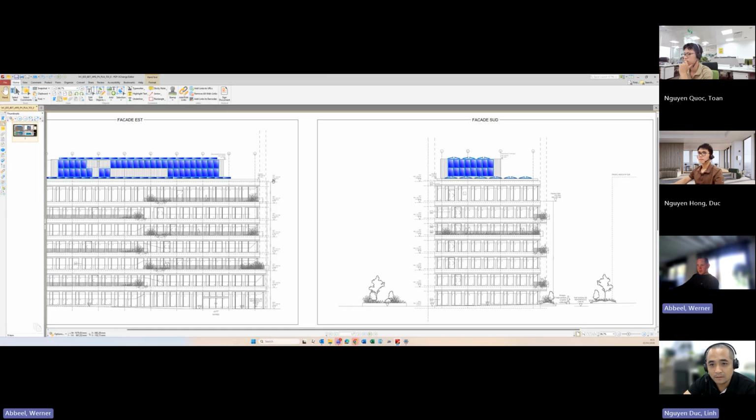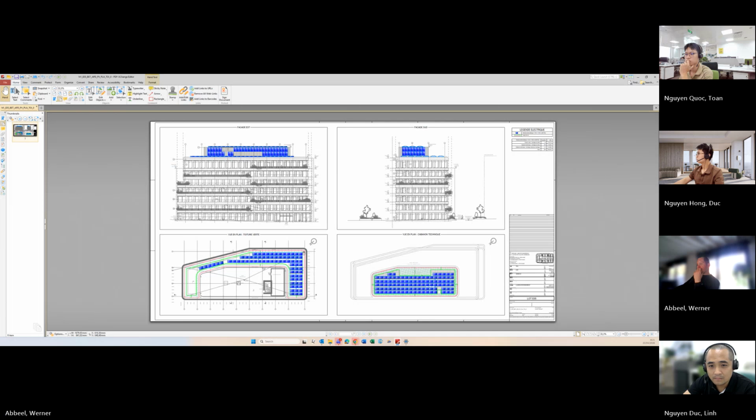Okay, two options. This is the building. What they did here, this is a technical roof, an extra floor. So in my opinion, this won't work. These are too short an amount of panels in one direction. So I would make this longer, so it comes till here. So I have at least 8, at max 18 modules. So it can be one string afterwards.